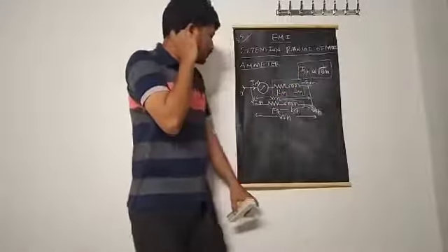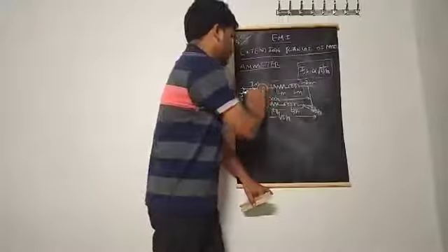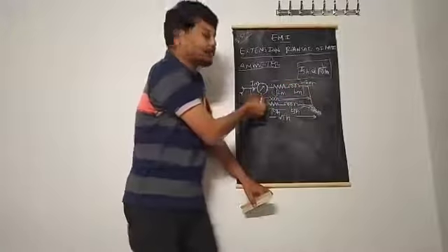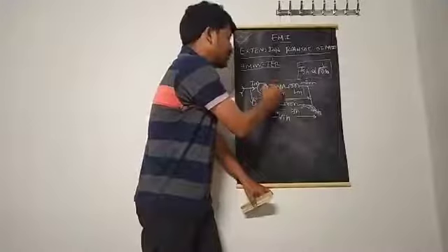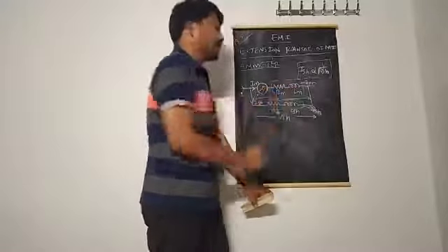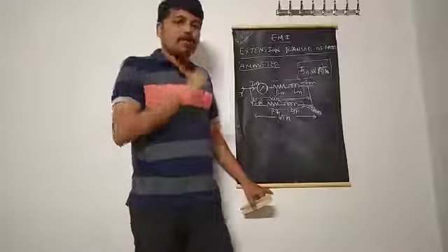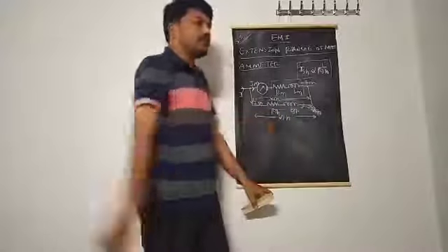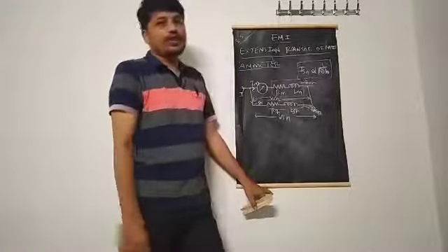For here, initially the meter without extension, this is the equivalent circuit. Look only at the upper part and leave the lower part. This is IM, the meter indication needle, that is the symbol of the meter, and resistance RM, the internal resistance of the meter, and LM, the inductance of the meter. In this moving iron instrument there is a coil and an iron piece. The inductance of the coil is LM and the resistance of the coil is RM, and we show the meter as a circle with an arrow mark. This is the existing meter.